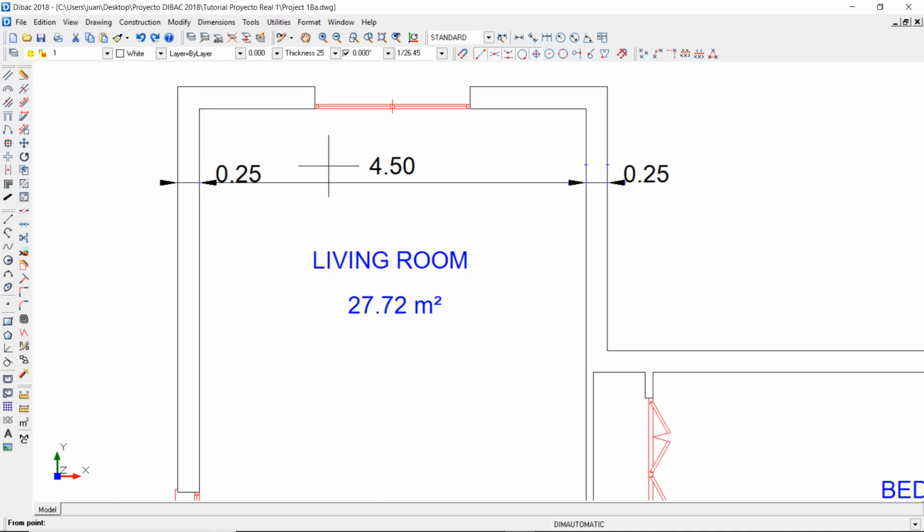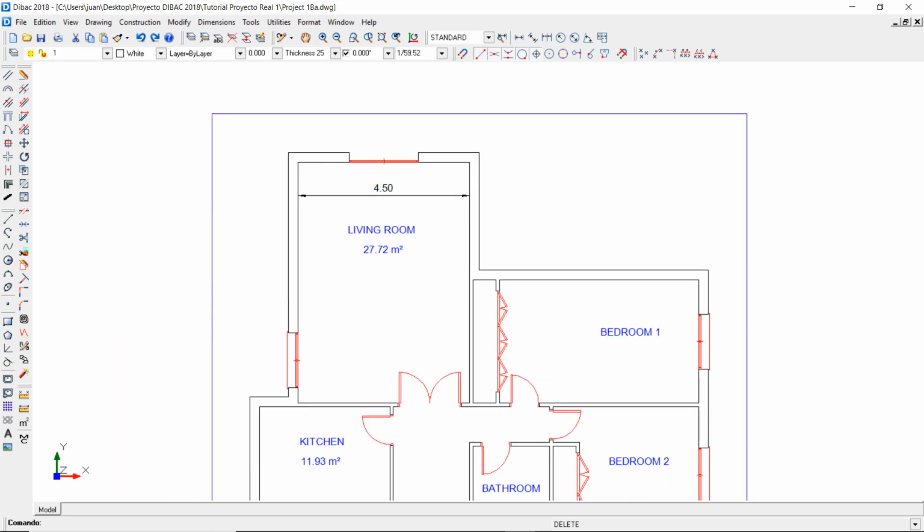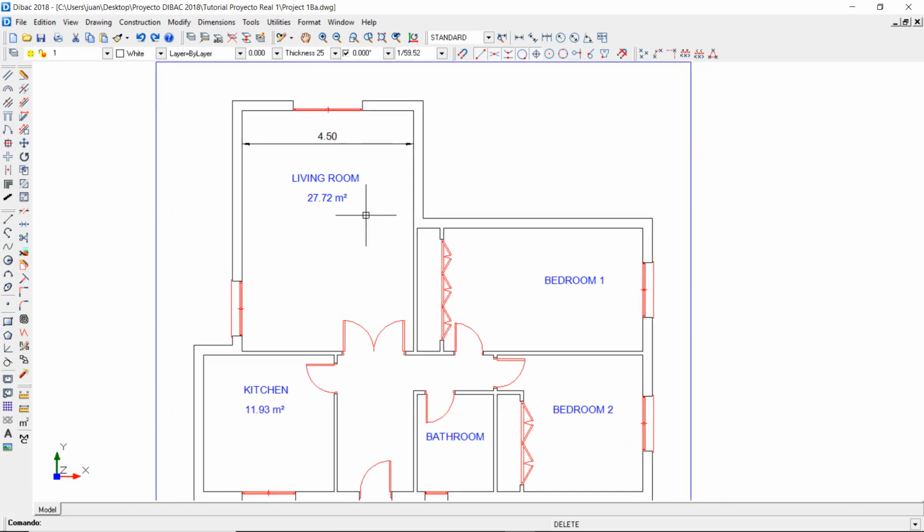Every value is a separated object, therefore I can delete the unwanted dimensions. I can select the dimension to change its color and move it. For this, click on the Move tool, select the dimension, and click outside to confirm the selection. Now you can move it vertically while the orthogonality is locked at 0 degrees. Then click again to confirm the new position.